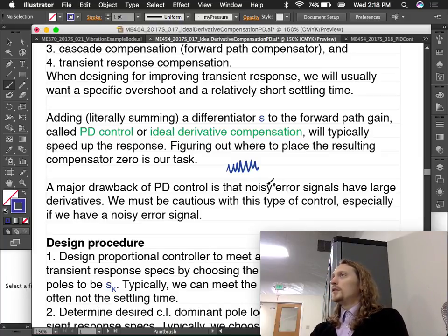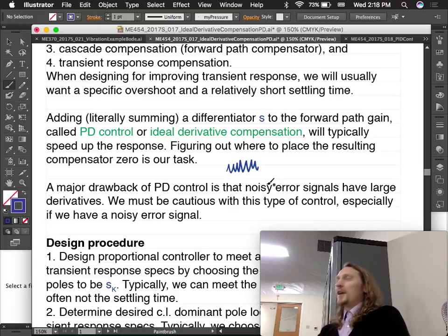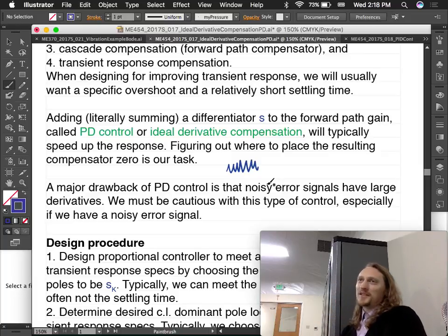Now you technically could move around the root locus with a pole, right? So when you do integral control, you could say, okay, we're just going to put in an integrator term, but we're not going to put in a 0 to cancel out that effect. And it'll affect the transient response. Maybe for the better. I mean, it's possible. It might not be bad. It could be good. But most likely you don't want to do that.